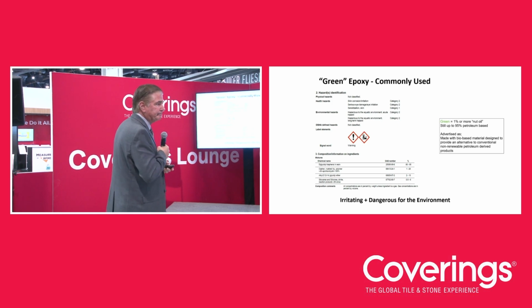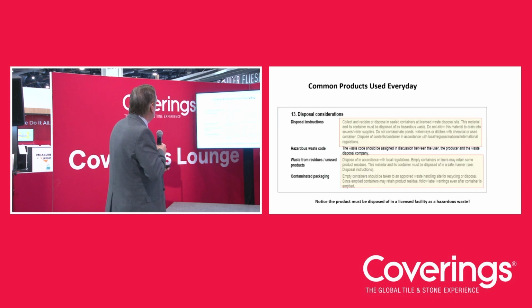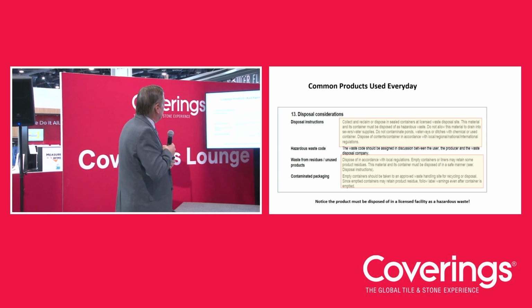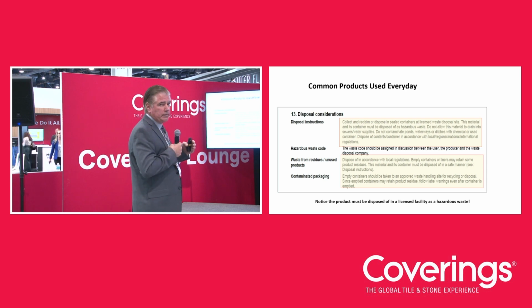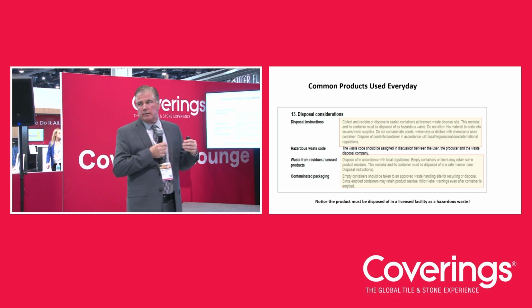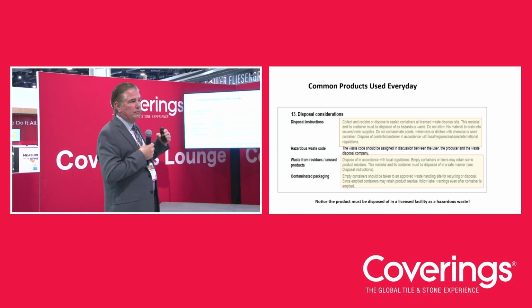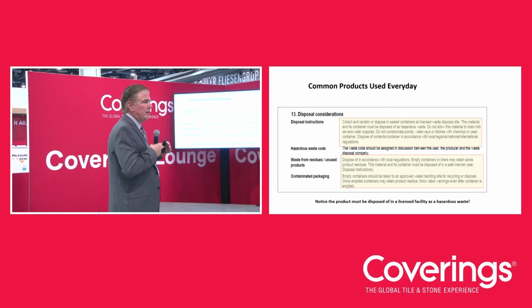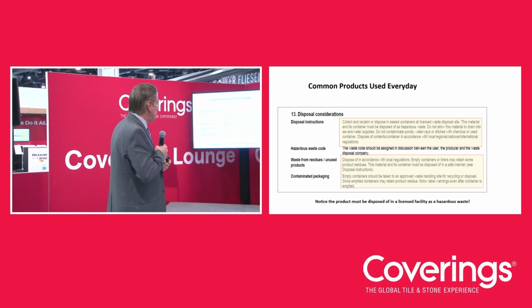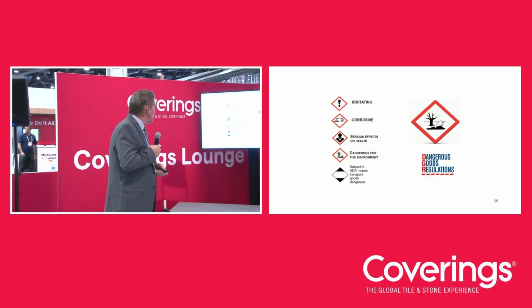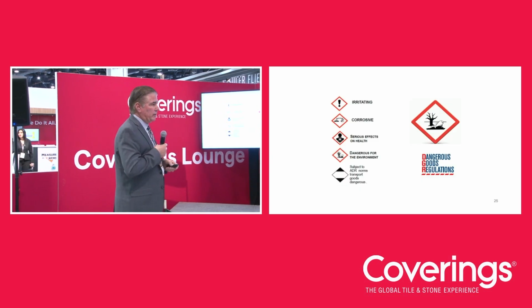This shows in the SDS the disposal considerations. You have to collect and reclaim, or dispose in sealed containers at a licensed waste disposal site, this particular epoxy chemistry. Even the buckets it was mixed in need to be taken to a licensed disposal site and disposed of as hazardous waste. Most people don't drill into the SDS to understand this, but this is not something you can just throw in the normal garbage. Again, these are the icons to be looking for in the safety data sheet.